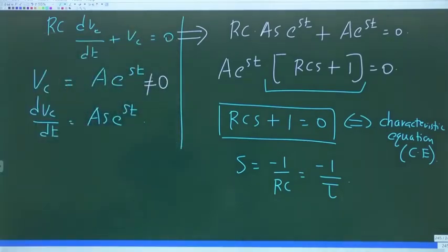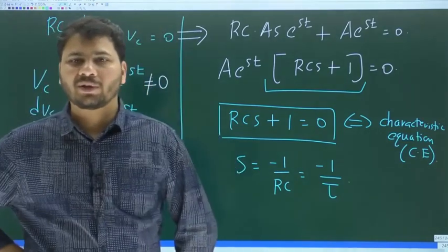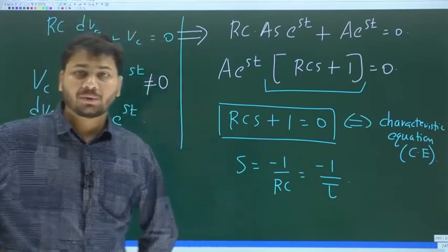Okay, system stability. What else will they decide apart from system stability? Please think in the context of the current discussion. Transient response, that's correct. Poles will decide transient response. Of course, poles also will decide whether or not the system is going to be stable when you apply bounded input and so on.